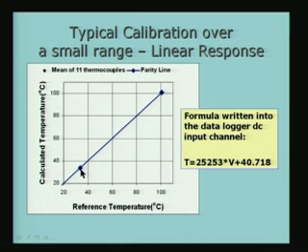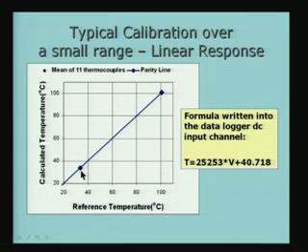This is nothing really. The only point is I have taken the mean of 11 thermocouples and they seem to follow this rule very well. In fact, all thermocouples do not follow the exact values given here. So, they have some variations amongst them, and on the average, there is an equality between the calibrated or the calculated value and the reference temperature. That means this figure is really giving you only part of the answer. The correct answer is here. So, what I am going to measure is this value V. This V is going to be measured by the data logger or gathered by the data logger.